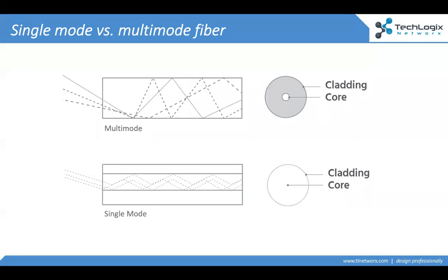And this is why single mode, the yellow cable with a really small core, goes really long distance, I mean miles, thousands of miles. This is a cable we use between continents, between cities, between buildings. Single mode is that cable. But we also use it in pre-wire because you can put that same cable in the wall, and it's going to go really far and support a really high bandwidth because those signals, those lasers, the optical waves, stay in phase.